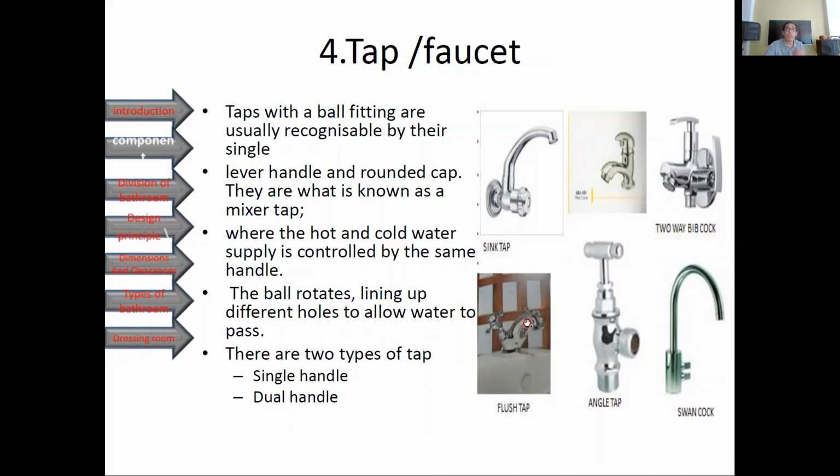There's also what you call a ball valve, no? That controls the faucet. Sometimes it's not a ball valve. Sometimes it's a screw type, no? With what in Tagalog is called sapatilla. It's a rubber that makes the water stop. No? The screw pushes the sapatilla to the point that the water will not penetrate, will not pass through it. So there are different types of mechanism inside the top of the faucet.